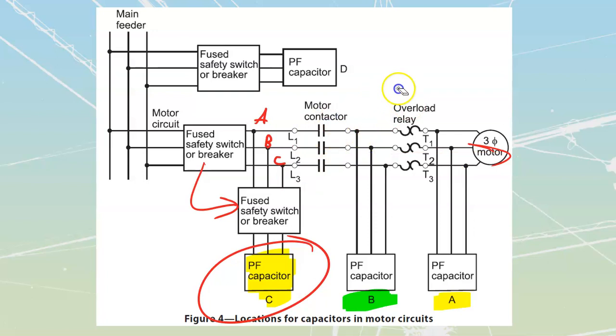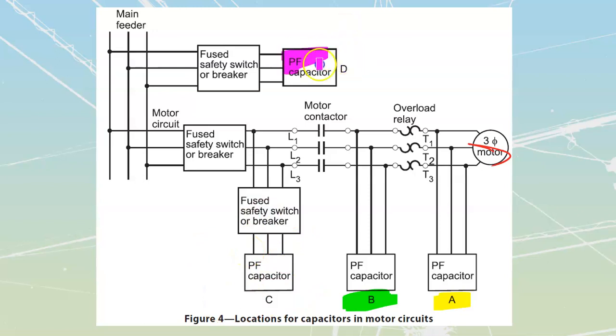The last location that we're going to take a look at is just going to be what we refer to as feeder correction. That's going to be my D location up over here. That D location would be where I'm going to get a very large bank of capacitors, usually hundreds of tiny small capacitors, but then I've got a whole cabinet full of contactors and automatic sensing relays, current relays, and things like that that are going to be continuously reading what's going on inside of my mains.